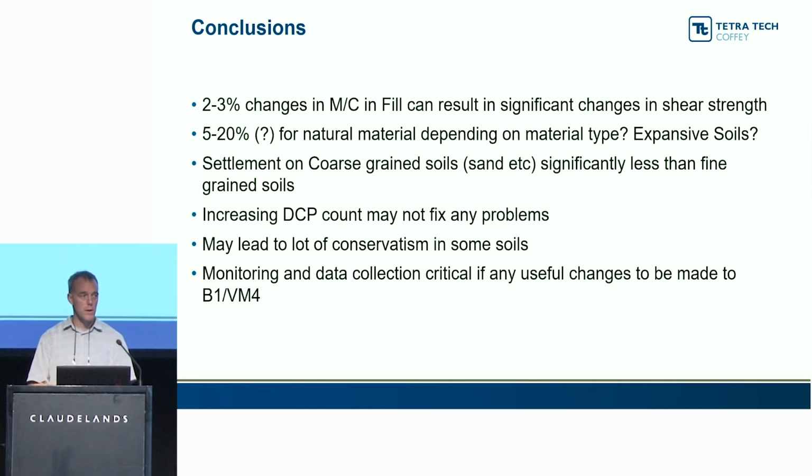If you compact the soils at too low a moisture content, you get too much air voids, and it works like a sponge. It'll suck the moisture in, and you'll see it on site. It's all bouncy and soft.